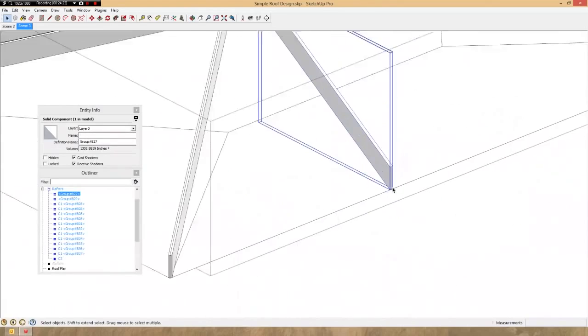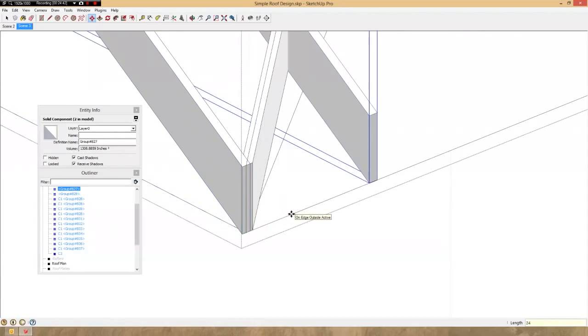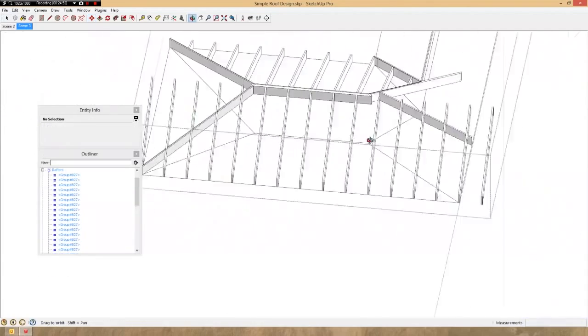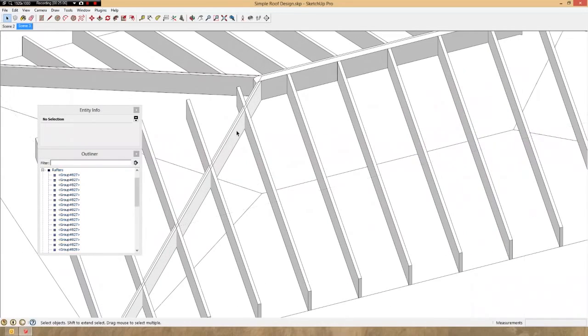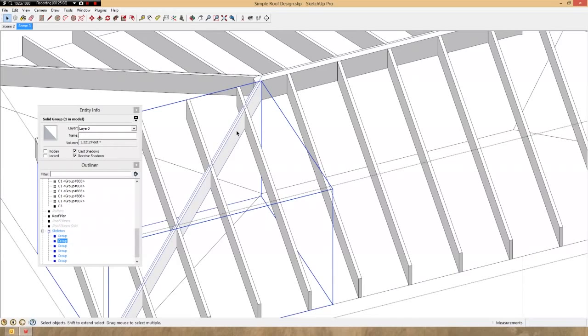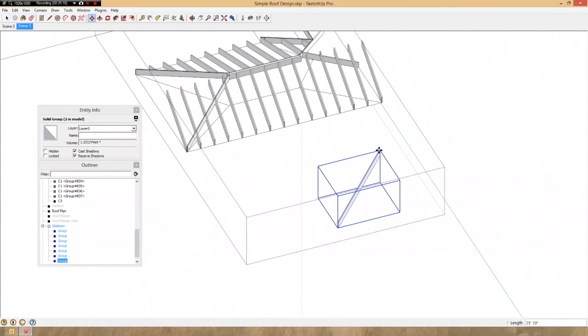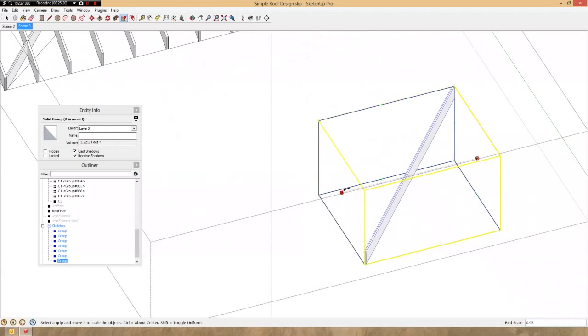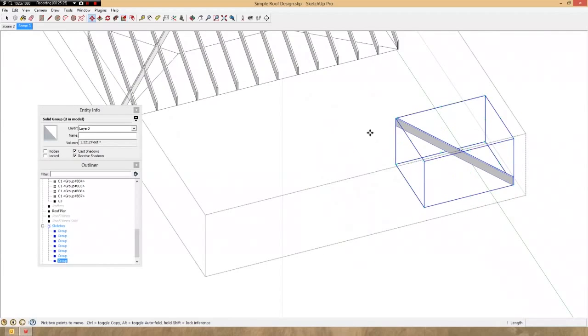And so on until we finish and edit all of the hips. We need to copy a hip over to the right side where it's missing. So we'll select this hip here. It's a component. Go ahead and make a copy of it, drag it over, select S for scale, type in -1 to get a mirror image, and then drag it in place.